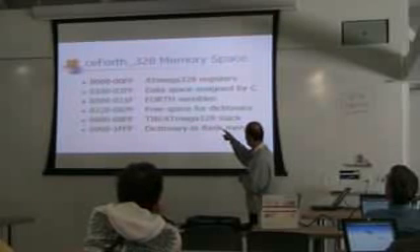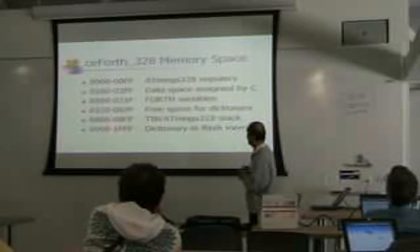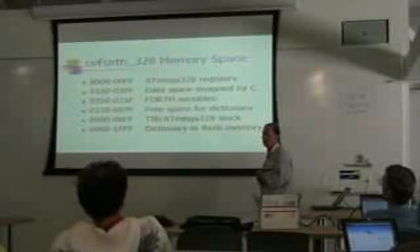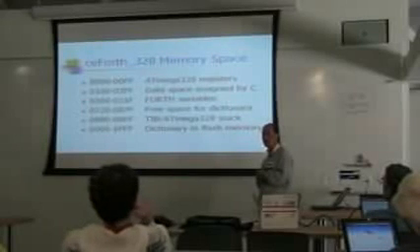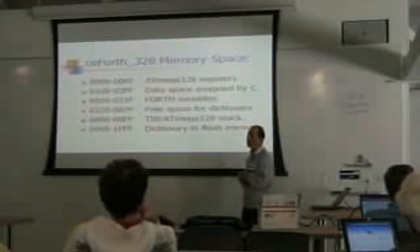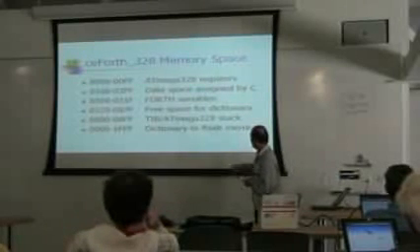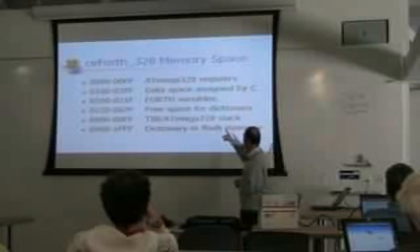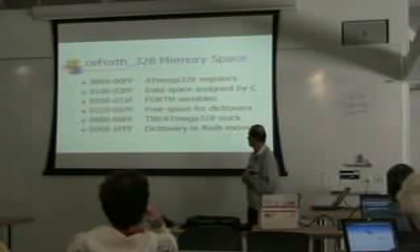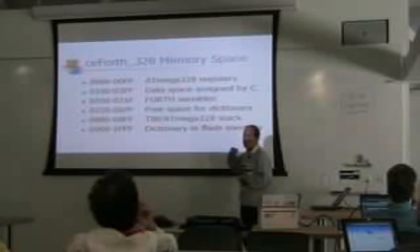I use the first 32 bytes to store variables, initialized to false, and the next whole bunch of memory, about 1.5 kilobytes of free space, is where you can grow the dictionary. On top of the memory map, there is an area where the TIB, terminal input buffer, and also the ATmega hardware stack are.